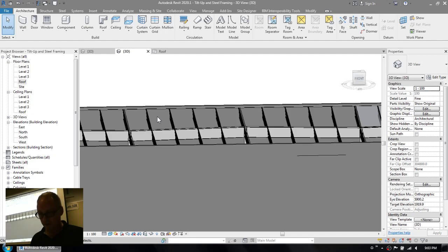So there's a sloped structure, HSS placeholder, placing columns first, editing structure after placement, so that's using detail lines just like I showed you, modeling it roughly in 3D just to get the members into place, and then use those detail lines and the align tool and align that structure exactly into place.